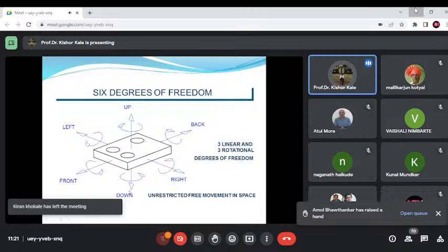That is the bottom surface of this plate. So if you see this as a plate, as your product, you have to define three different points on the plane. It ensures that the first step is established by three points. So you have to specify any three points on the bottom part of the plane. So that will be your plane A. So that becomes your primary datum.